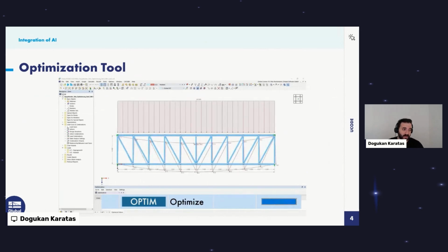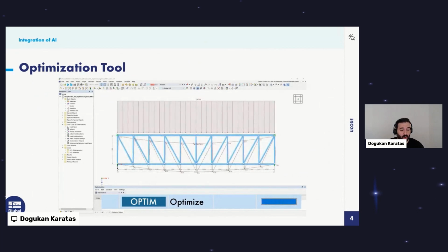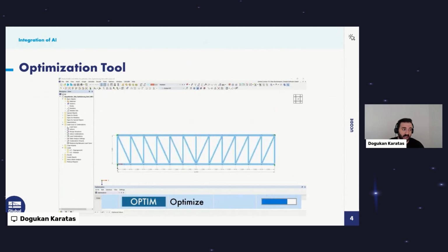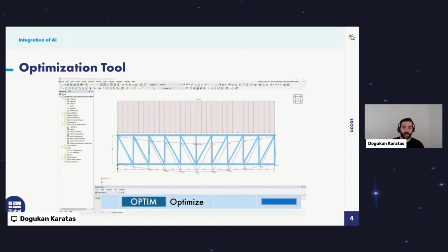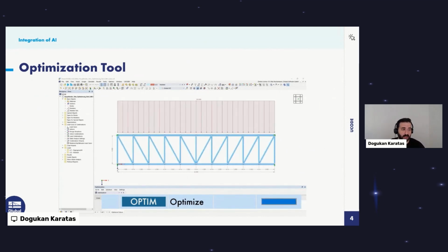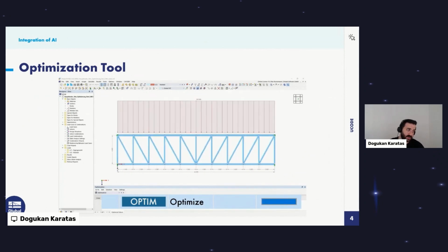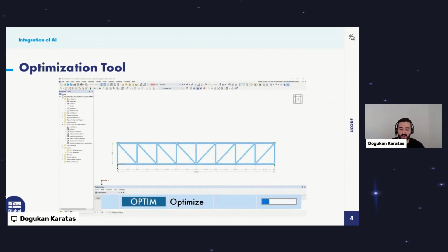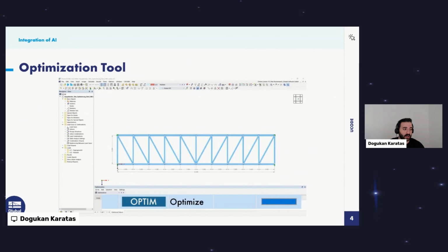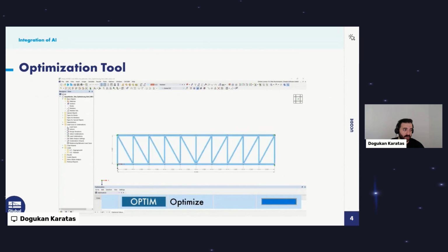The first point I'd like to emphasize is that the integration of AI into Dlubal Software products is not a new thing. We already have a tool inside RFEM that uses AI for optimization. Our optimization of costs and CO2 emission estimation uses the artificial intelligence method called particle swarm optimization to find suitable parameters for parameterized models or blocks to meet the usual optimization criteria. On the other hand, this add-on estimates the model cost or CO2 emission by specifying the unit cost or emission per material.